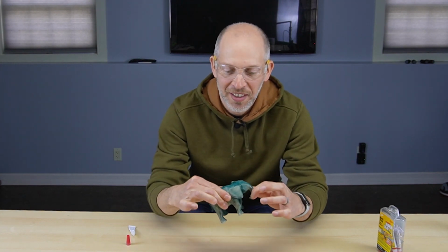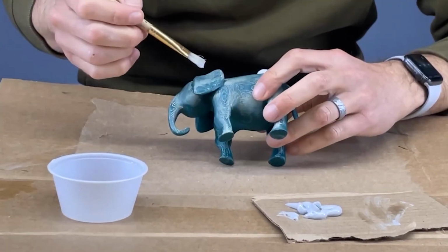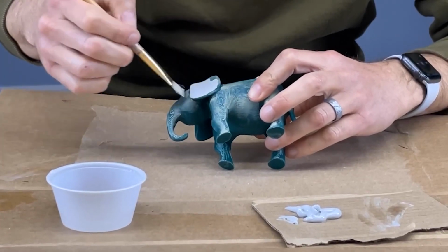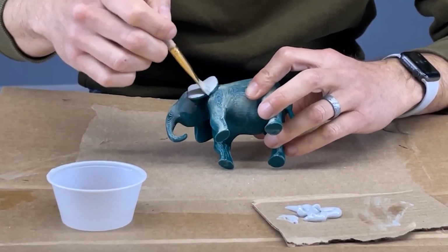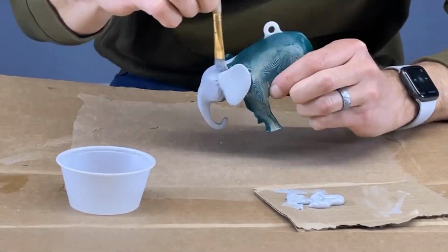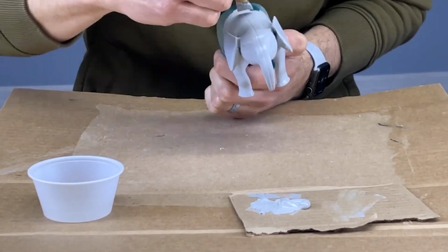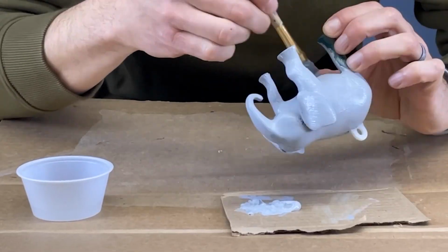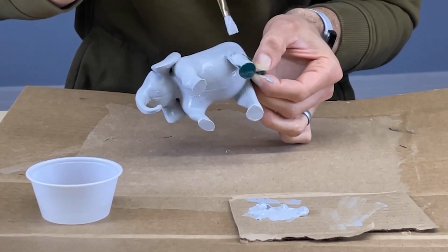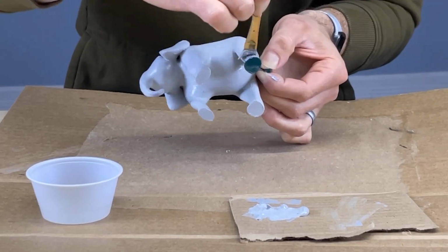It happens fast. Using a small brush, I applied a thin coat of gray acrylic paint. When it dried, I noticed that the 3D printed layers were still a little bit visible. So I sanded the model down to remove most of the surface paint, leaving only the paint that filled the low spots. Then I painted the whole elephant again, and this hid the layers even better.